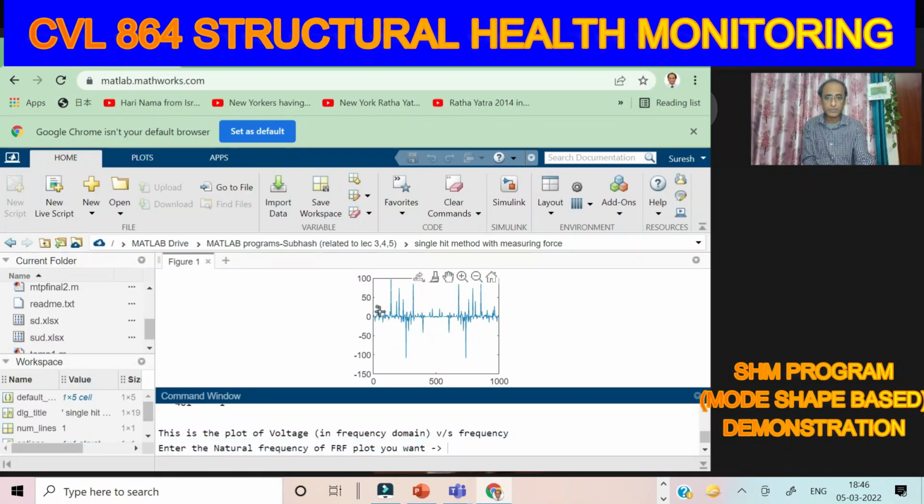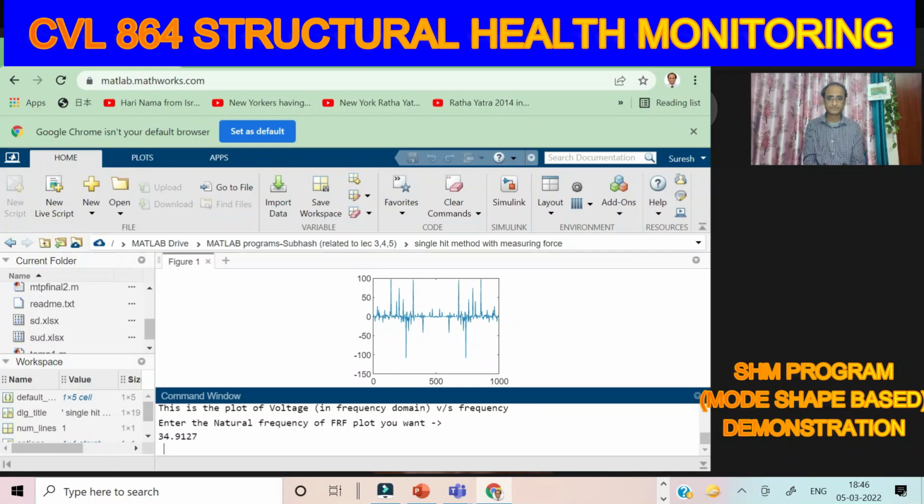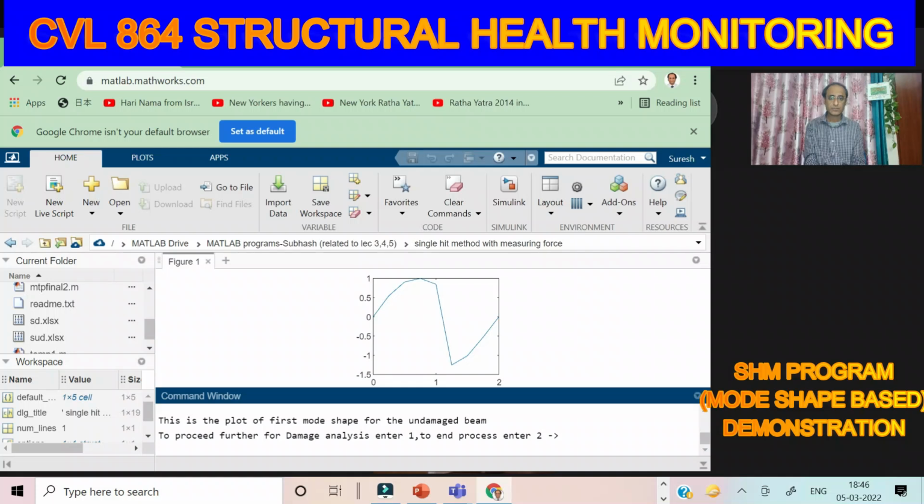The value is 34.9127, so let me enter here 34.9127. Now it asks whether the sensors are placed equally or not. In our case, the sensors are all uniformly placed, so we enter 1. Now it has plotted something. Can you identify which mode shape this is? Second. Second mode shape, yes. Sorry, second mode. This is the second mode shape, so the second mode shape is identified.